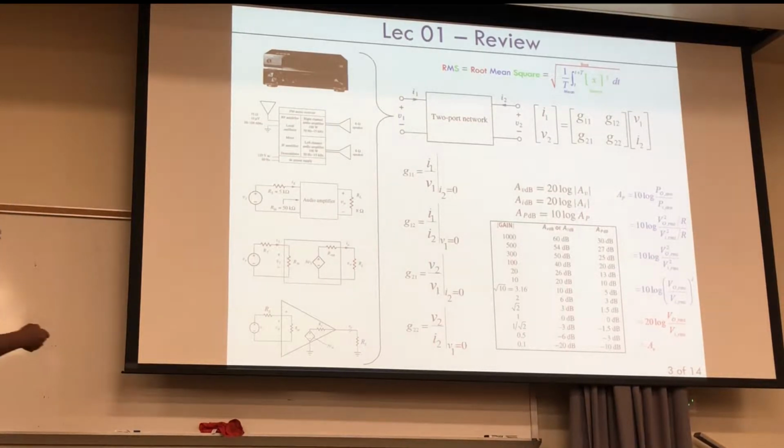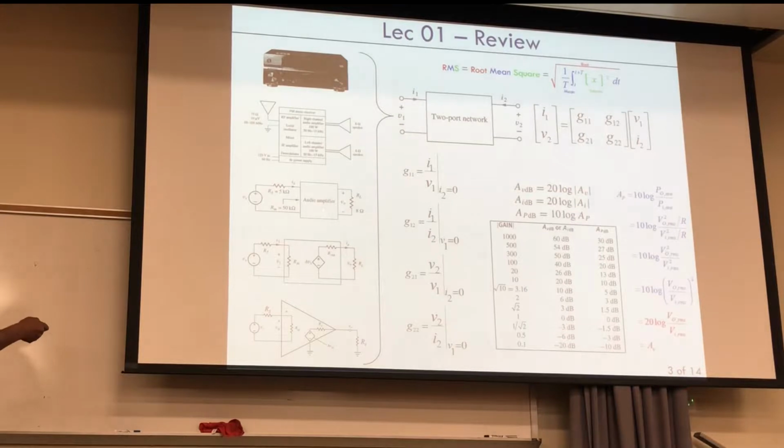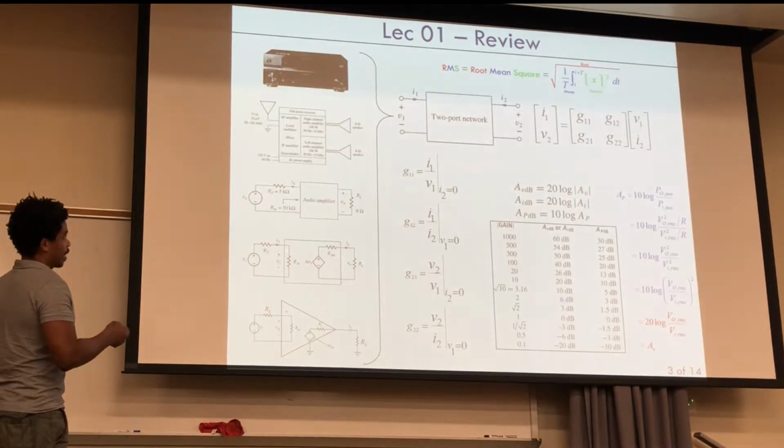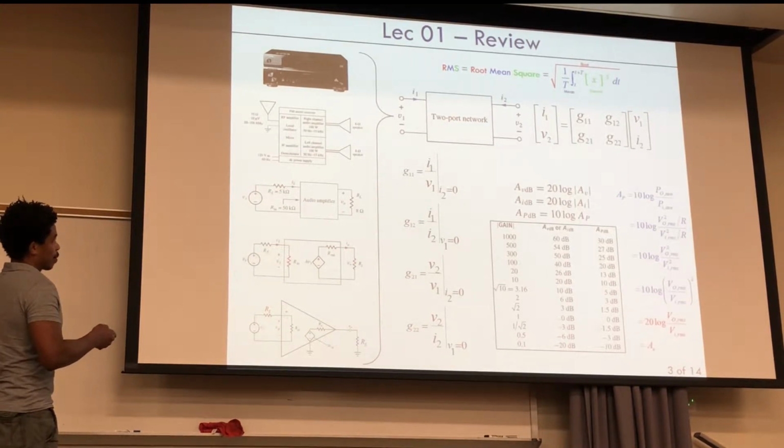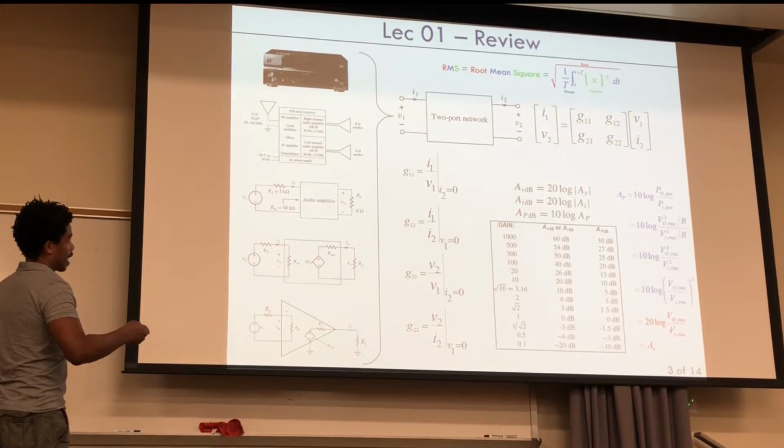And here's another abstraction of that where you can take this thing right here, this box, and say, well, here's just my amplifier. The antenna is supplying some type of voltage, really small, but it has some resistance to that antenna, right? And here's the speaker, which can be lumped into a resistor. And this part right here can be abstracted to something more simplified, where you can model it like this, where it has some type of resistance coming in, some type of resistance that you can see if you're looking at it from this side, and you're amplifying it right here.